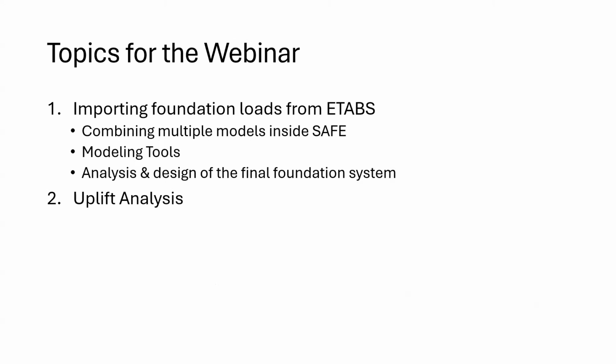Right. Now, for today, we have taken up the foundation system. Specifically, the slab system will be covered in another session. So the first one would be about a complete model, but we will take two ETABS outputs of the loads from above, and then we'll try to combine them, showing how to do it in the SAFE. And we'll also explore the modeling tools available for creating such a combined raft. And finally, we'll perform the analysis and design of the system.